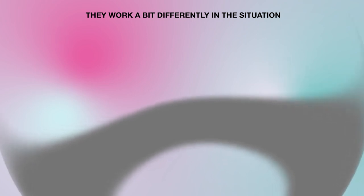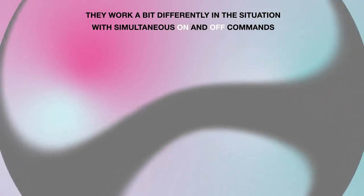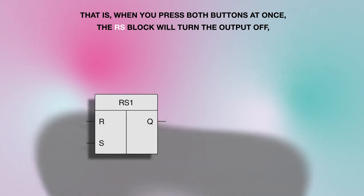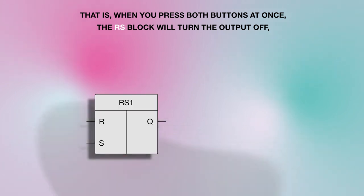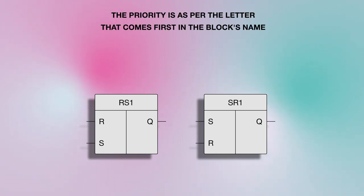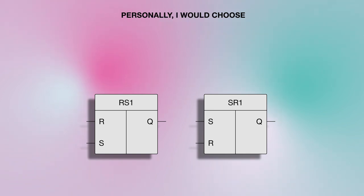So why are there two of these blocks? Actually, it's quite simple. They work a bit differently in the situation with simultaneous on and off commands. That is, when you press both buttons at once, the RS block will turn the output off, while the SR block will turn it on. The priority is as per the letter that comes first in the block's name.